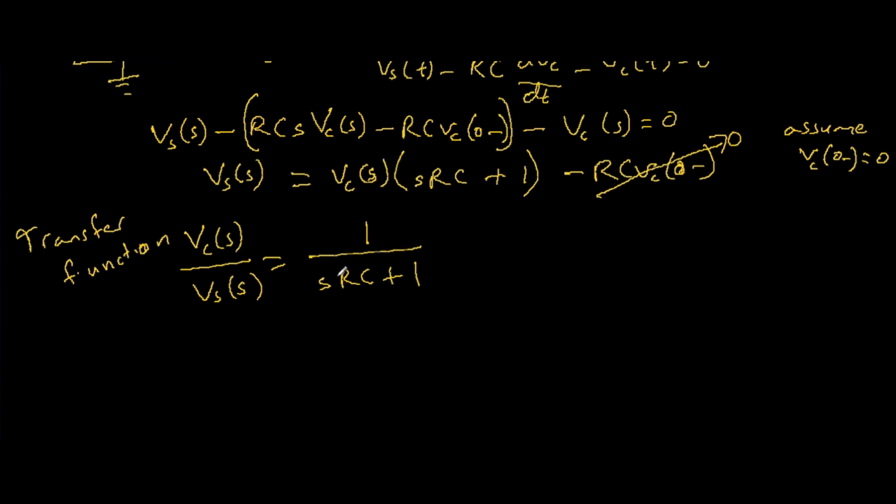So 2 more things I want to mention about this particular transfer function. First of all, this is a first order system. So this transfer function tells us it's a first order system. Now we know it's a first order system because the highest power of S in the denominator is 1. So it's a first order system.